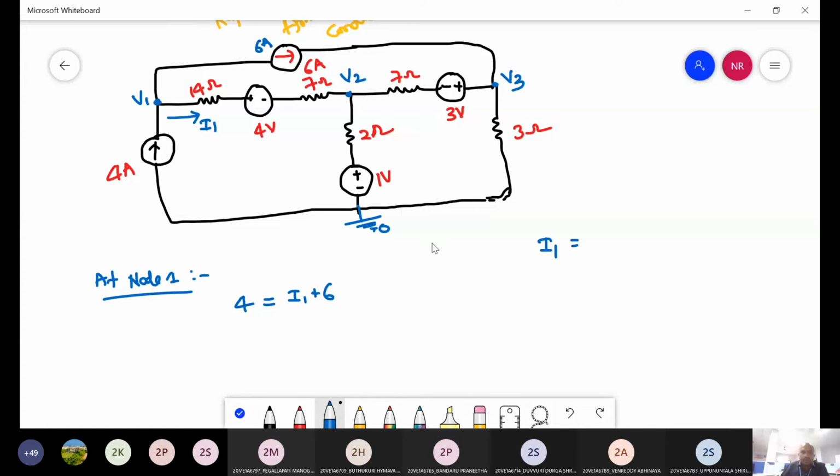How to write down I1? Here in this I1, current is equal to, what is the formula? Voltage by R. So from this point to this point, the potential difference is V1, then here again plus 2 minus 4 volts, voltage difference.